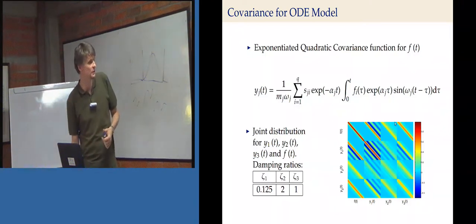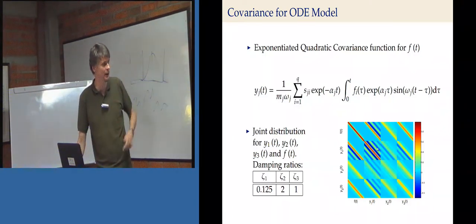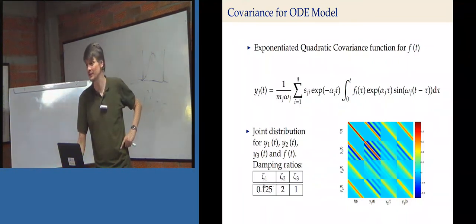So what we can also see is the cross covariances. What do we notice about this one? Got these bands, doesn't it? In fact, the values go negative. Why is that? Think of the damping coefficient. That's a resonant system. So it's got a natural frequency, and the distribution of these bands are associated with the natural frequency. These overdamped and underdamped systems don't exhibit their bands unless they're cross-correlating with the resonant system.